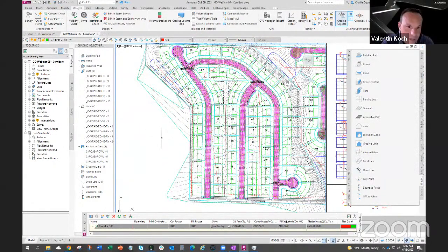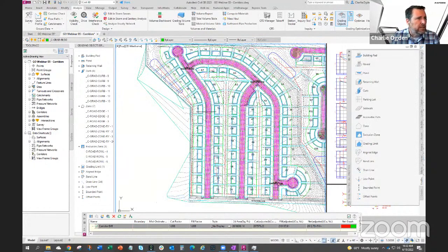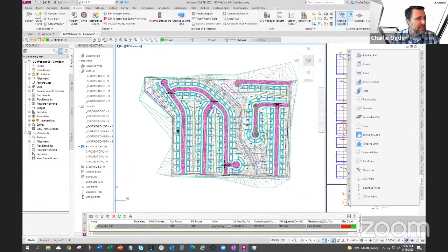We can add some building pads now. Yeah, so we can flatten these areas where our buildings go. Now these I just created roughly from the front yard and side yard setbacks. I just created a big rectangle, offset back, I think 30 feet or maybe more. They're not building shapes. I just created some rough shapes just to flatten out part of the lot where the house might go. You could, of course, be a little more careful about how you're creating these and place them a little bit better.